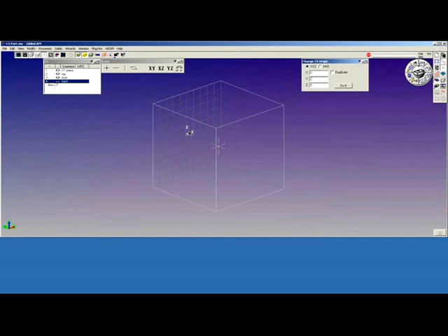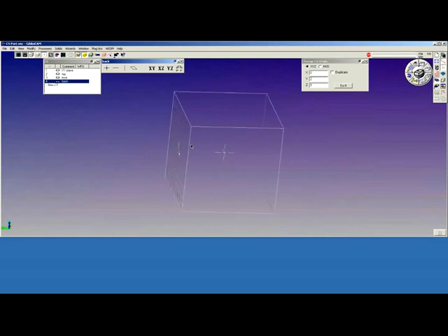The origin must be toggled to show the negative sign on this side. In our coordinate system palette, the last tile is toggle depth. If I click on this tile once, notice that it inverts the markers and shows the polarity as negative to the inside of the cube. So that appears to be correct. Now, the tool approaches from the positive side or outside the cube.